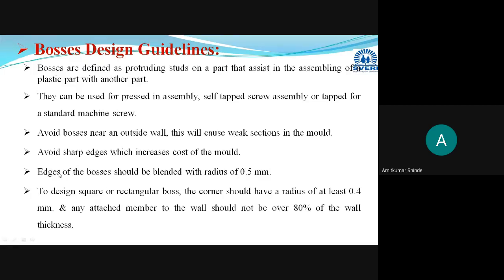Instead of using sharp edges, give some radius or fillet there. Now to design a square or rectangular shaped boss, you have to provide a radius of at least 0.4 millimeter.